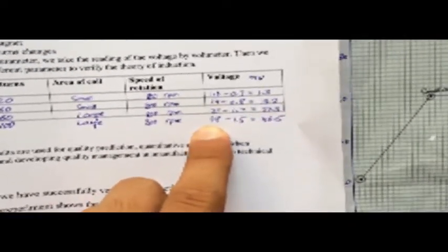So here are those four readings we took. This is the number of coil column. This column represents the area of the coil. We have two standards here, small and large. The DC motor we are using revolves at 200 RPM, and these are the corrected values of voltage. These are the voltage values, and these the stray voltage. When we subtract stray voltages from the value we took from the voltmeter, we get the accurate value of voltage.